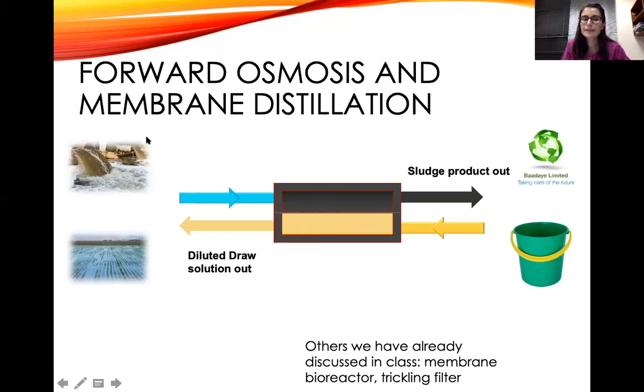So for that, I added the membrane distillation process, which basically means that once this is done, I subject this water to heat, and the water vapors then can go through this membrane. So this membrane is water loving, this membrane is water hating. So it's only allowing water vapors to pass through here. After I do this, I'm heating this stream, and I claim all the water in the form of gas, and that goes past the membrane, which wouldn't allow anything else.